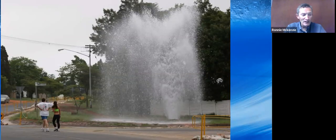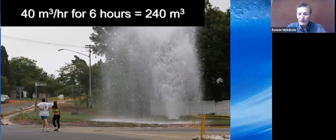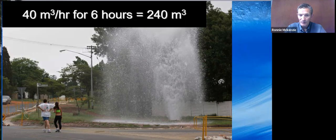This is another one. It's a slightly bigger one. It's also a mains leak, obviously. This particular one was running at 40 cubes per hour. And you can see there, this one ran for about 6 hours. And during that time, it lost 240 cubic meters of water. So it's a bit more than the previous one I showed you.